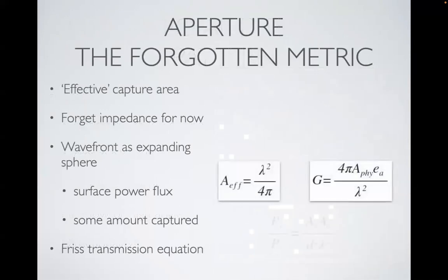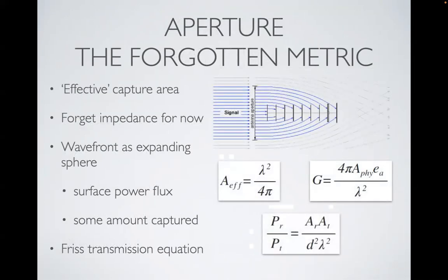Now, there's this other parameter that we often don't talk about in ham radio, and that's aperture. Aperture is kind of like gain. Just wanted to let you be aware of it, just if it ever comes up. Occasionally it does in ham radio. Usually in non-ham radio context, people talk about apertures and antennas. It's kind of like the opening on a telescope or something like that. How much of that light, which in this case is RF energy, can get in through that opening.